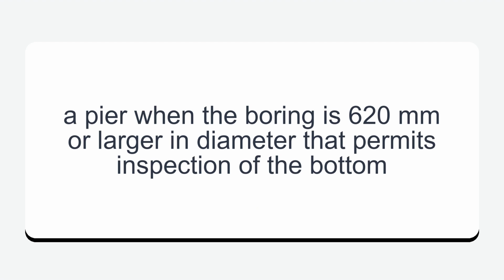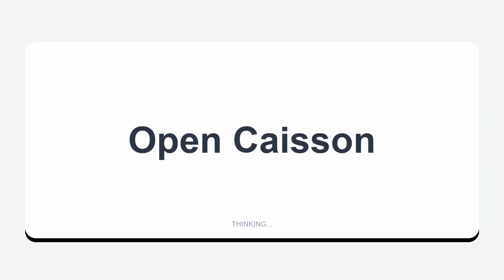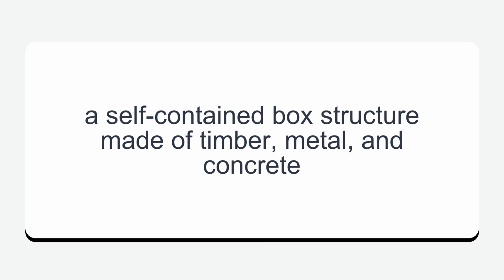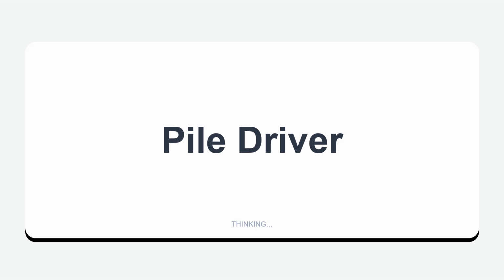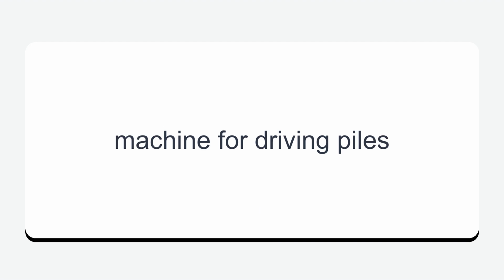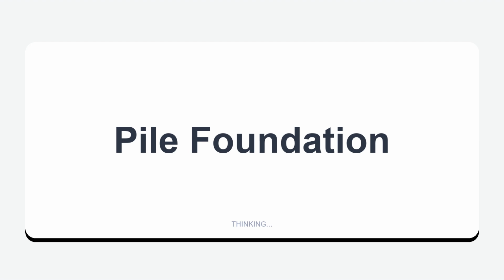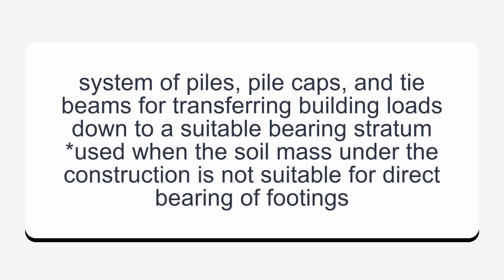Appear when the boring is 620 mm or larger in diameter that permits inspection of the bottom. Open caisson: a self-contained box structure made of timber, metal, and concrete. Pile driver: machine for driving piles. Pile foundation: system of piles, pile caps, and tie beams for transferring building loads down to a suitable bearing stratum, used when the soil mass under the construction is not suitable for direct bearing of footings.